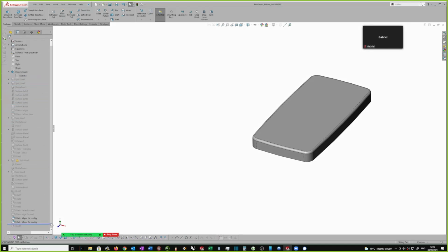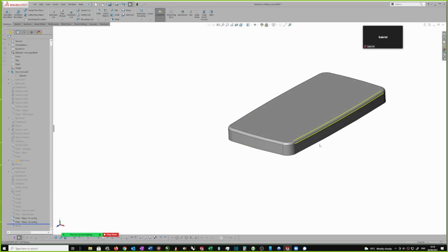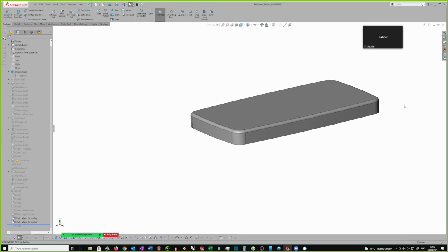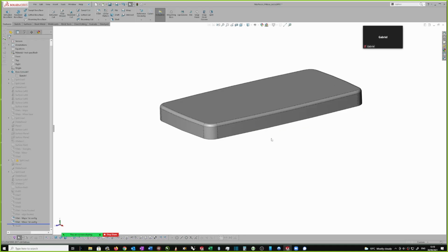like this. And the reason I'm rolling it back is because if I leave this line at the bottom and I now want to put a taper in, because I've taken the taper out, it's going to put the taper in after the two fillets. And that's bad. We don't want to do that, because then that's going to make this fillet taper upwards from one radius to another, which is more difficult to tool, and you're sort of making things more difficult.